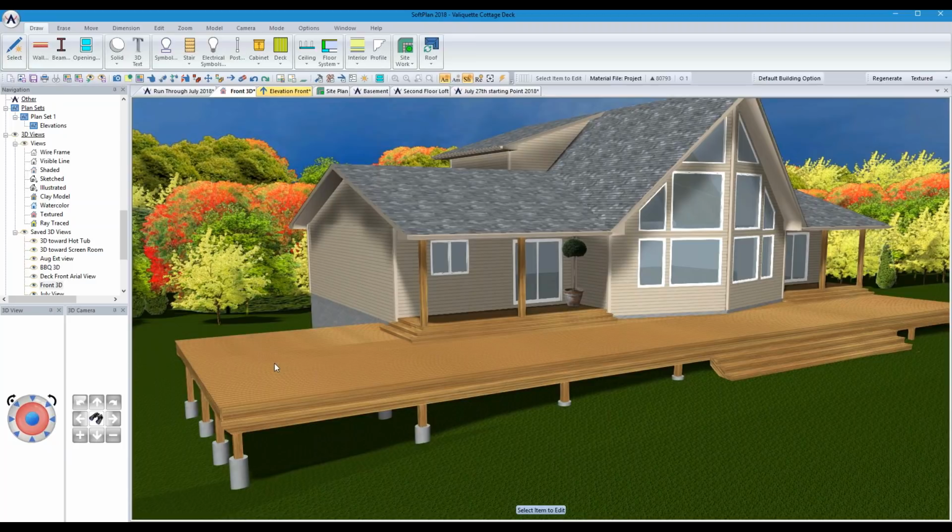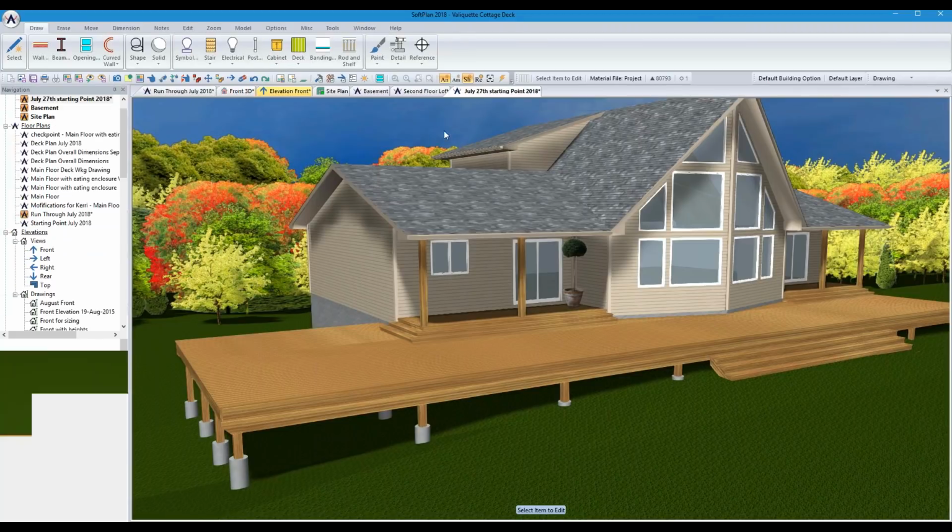And what we're going to do to start with that is I'm going to draw some posts in. I'm going to draw some 6x6 posts. I'm going to upsize those to about 8x8s. And then I'm going to use a wall that I've defined. And there's also one in the actual shipped wall definitions that you can use that will suffice as well. The one that I've put in actually has a framed in bottom area that has siding on it. So that's the only real difference.